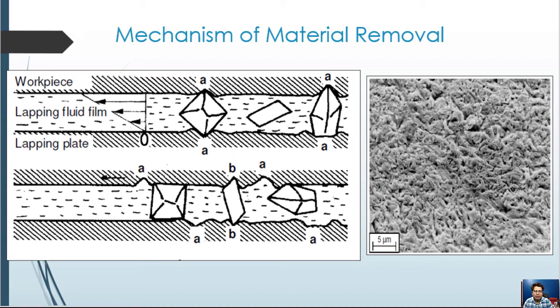The properties of the lapping discs are determined by both geometrical factors and working material. When machining workpieces with larger surface, disc grooving is necessary in order to ensure that there is an even supply of grains at all points in the lapping disc. The abrasive materials mainly used in lapping processing are silicon carbide, Al2O3, that is alumina, boron carbide and increasingly diamond.